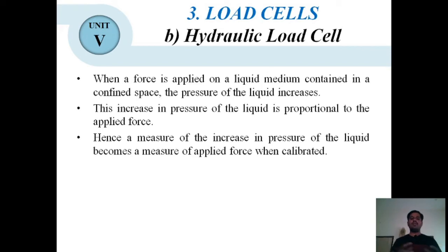This increase in pressure of the liquid is proportional to the applied force. Hence, the measure of increase in pressure of the liquid becomes the measure of applied force when calibrated. As we go on increasing the pressure, this change in pressure directly gives the change in force.